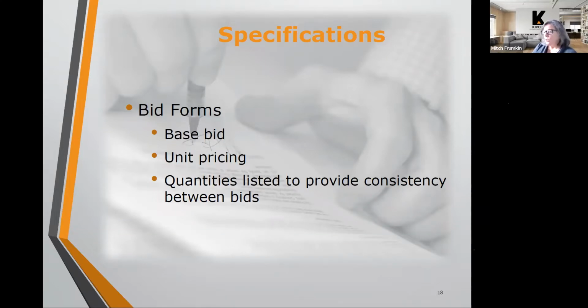Now, as I mentioned, there are unforeseen conditions in pretty much every pavement project. And the more damaged your pavement is, the more surprises there are. The unit pricing seeks to capture those incidental items that typically come up in a pavement project, but you don't necessarily know you need yet. So that might include base course repairs, removing and replacing that base course asphalt.